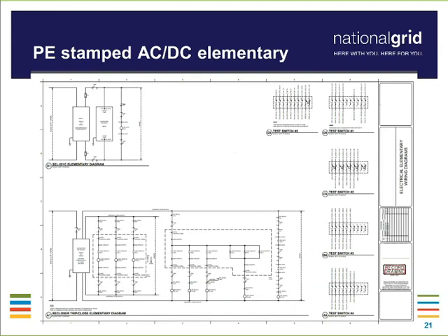Okay. The AC and DC elementaries. So the elementary drawings are, well, sometimes they may not be required. If you have a fused service, there's not an elementary drawing to be had. But if you had a device that had an interface with some kind of a logic scheme, a protective logic scheme that may be embedded within a controls package or a standalone relay that integrates with something like a recloser or a breaker, if that scheme is necessary for the operation of the generation or the DER, we would want to see that.